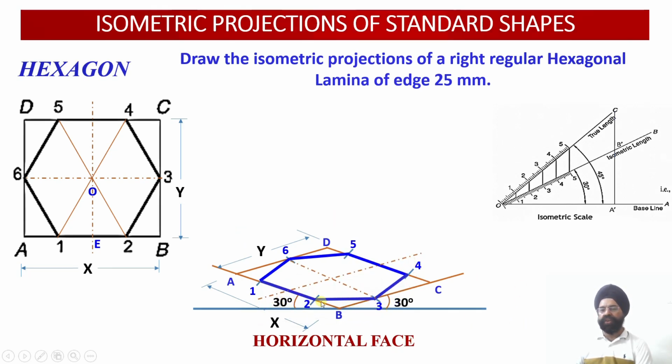And in this construction, one thing we have decided is that the longer edge was lying here, shorter edge was lying here. So here we are assuming that this edge of the hexagon is lying parallel to the VP. If we are given that this edge happens to be perpendicular to VP, what do we have to do? We have to draw the longer edge over here and the shorter edge over here. So let us make that construction as well.